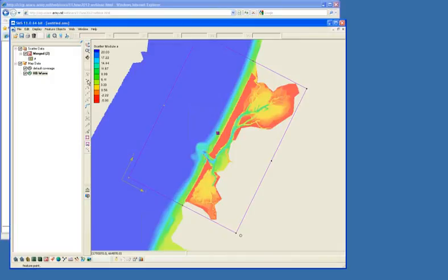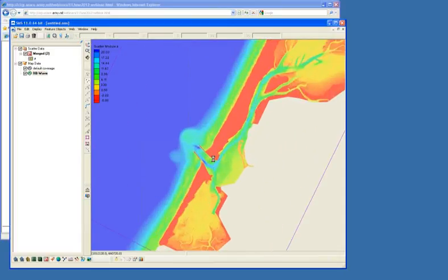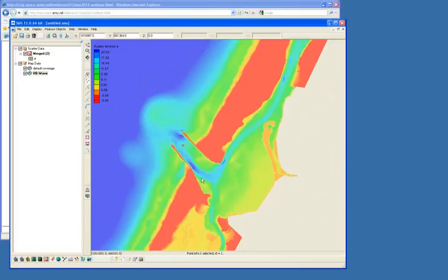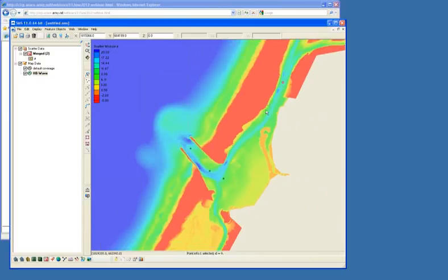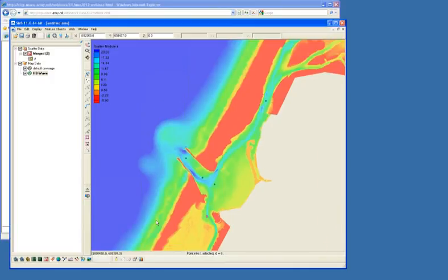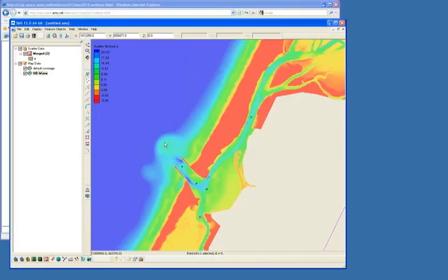So let's go ahead and create a point. Actually, let me make sure I'm in the right map data module. You can always see that it's feature objects, that would be the map data. We'll create a point, and I'll zoom in, and I want certain resolution through the inlet and maybe through a couple of these. I don't expect the waves to propagate this far up, but you never know how far they might go depending on the size of your bay. So let's just go ahead and add a little bit of resolution in just to make sure they can get as far as they need to.